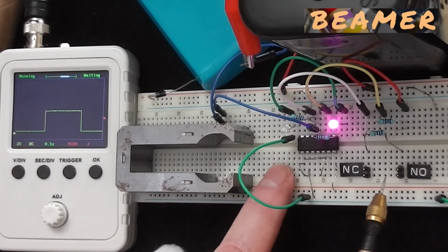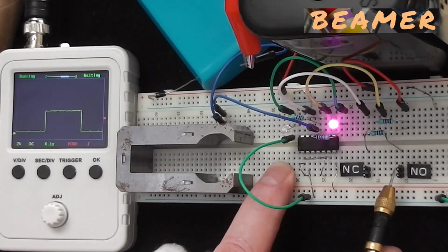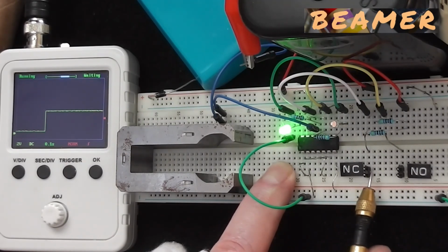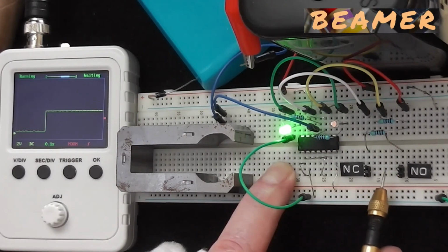Let's just give it one more go for the sake of it, shall we? Let's go. So the wiper of the micro switch is resting on the normally open contact. It moves across as the mechanical actuator starts to apply pressure on the micro switch, and eventually it touches the other contact, the normally closed contact. And then, it doesn't matter how many times that's pulsed, it remains the same. And then when the mechanical actuator moves away from the micro switch, the micro switch wiper will change state to the normally open, and it can pulse there as much as it likes.